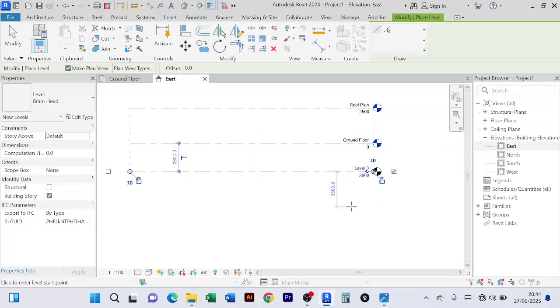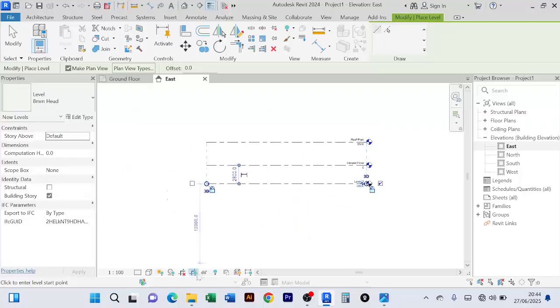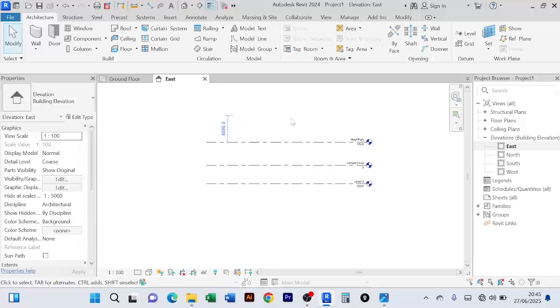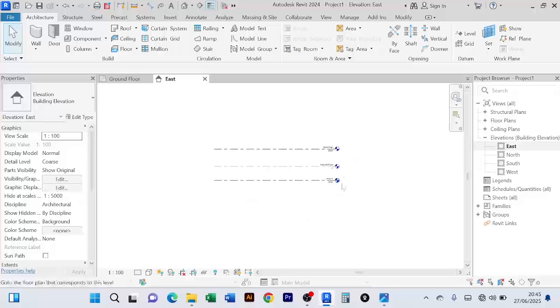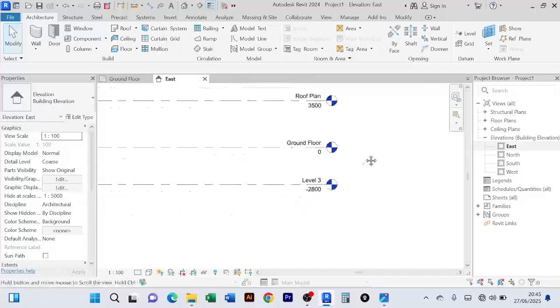It will align it perfectly with the previous level lines. Now, as I told you, when your cursor is like this and it is showing that it wants to do something, you can keep pressing escape key until these things disappear like that. You press until it disappears and the cursor is free from those commands.